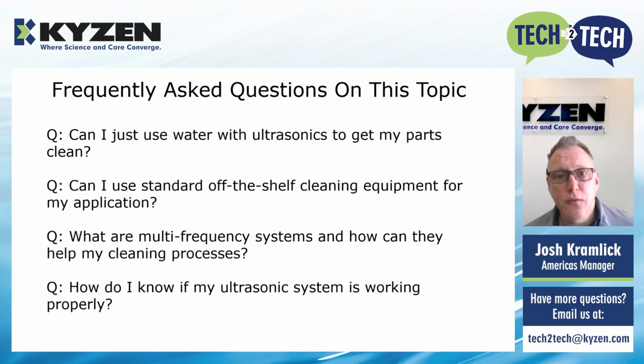Next question, can I use standard off-the-shelf cleaning equipment for my application? A lot of standard 40 kilohertz off-the-shelf units will work for the vast majority of your cleaning requirements. It's important, however, to note that we really want you to look carefully at the risk of damage, the efficiency of your process, and throughput as well. If you think that you're dealing with a more challenging application, it may make sense to consider something with a more tailored frequency selection.